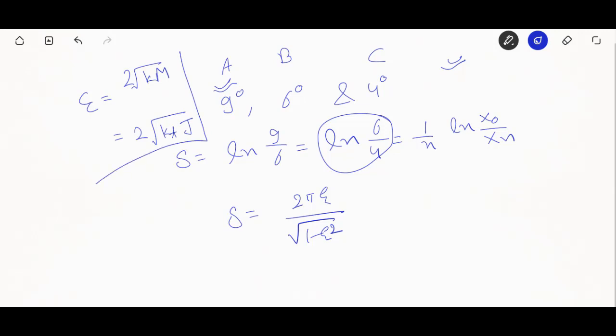Right? I hope you are familiar with the polar moment of inertia concept. It is always about the perpendicular axis, right? Inertia about this perpendicular axis. We are certain about the moment of inertia about the x-axis, y-axis, and the third axis, which is the z-axis. If you are calculating the moment of inertia about this z-axis, we can get it with the help of the perpendicular axis theorem, which is I zz equal to the summation of the moments of inertia about the other two axes. Now the important formula for the torsional case is this one. Now how to get this